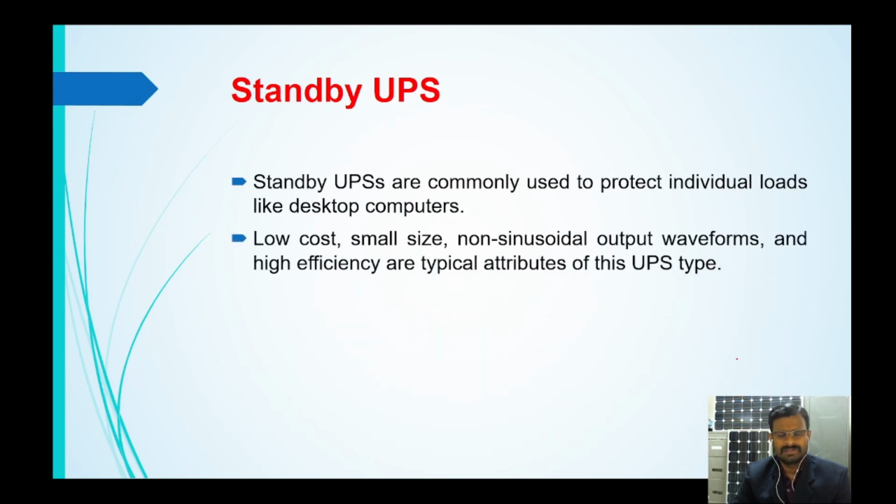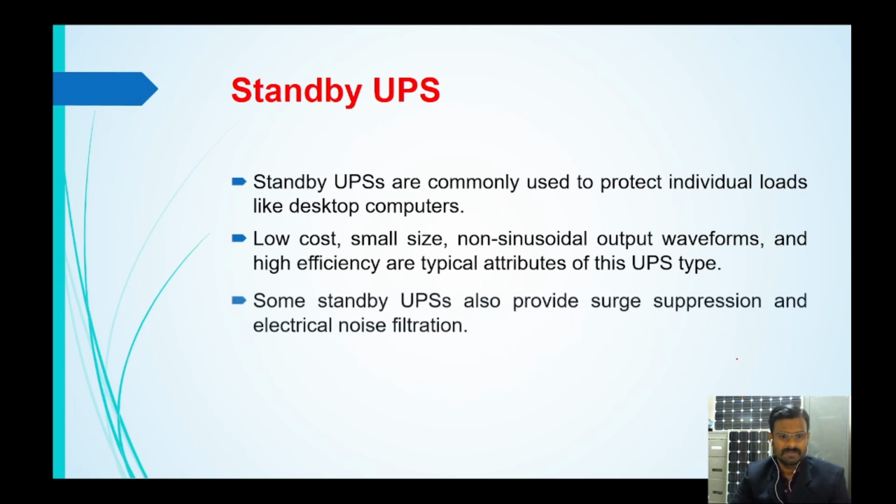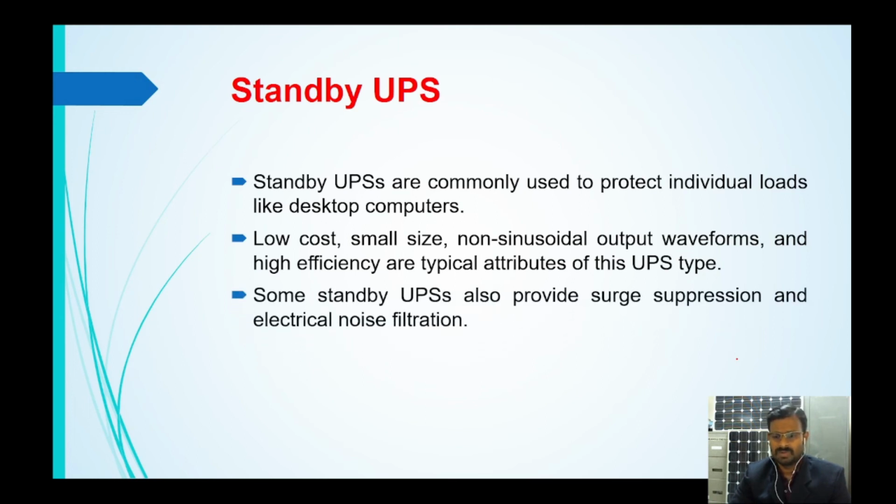Usually these standby UPS are used to protect individual loads like desktop computers. Low cost, small devices, non-sinusoidal output waveforms, and high efficiency are typical attributes of these UPS types. Some standby UPS also provide surge suppression, as I told you earlier, and electrical noise filtration.